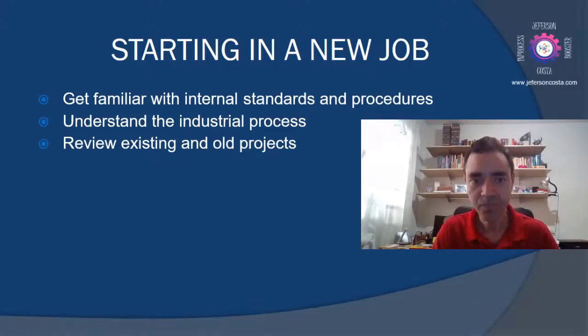And you need to be aware of that in order to upgrade or update all the documentation, because the most important documents for us chemical process engineers are the heat and material balance, because based on that you know what to expect from your plant, what's going in, what's going out. You need to have the process flow diagram, because it gives us the whole overview of the plant in terms of equipment and process conditions.